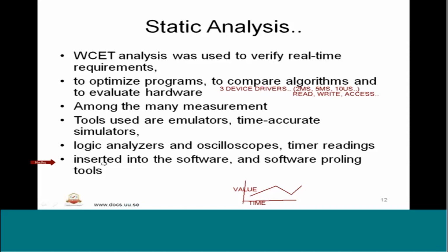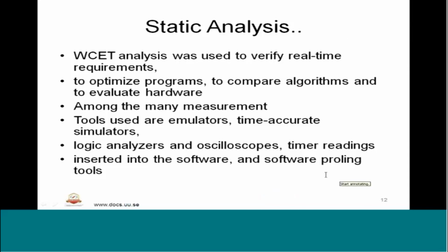And of course, we have inserted programs specifically for measuring this into the software, and we have the profiling. It's wrongly spelled here. It is nothing but the software profiling. Profiling is a very important aspect in embedded software systems. With the help of profiling, we will do the analysis of the timing that a procedure or the intended program is going to take. Okay, so that is about worst case execution analysis.